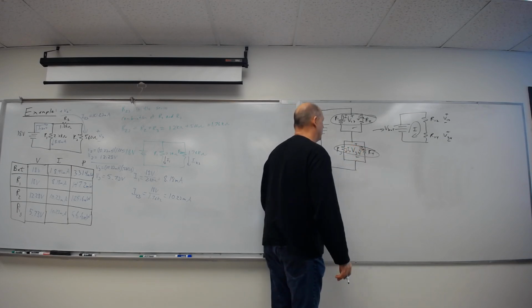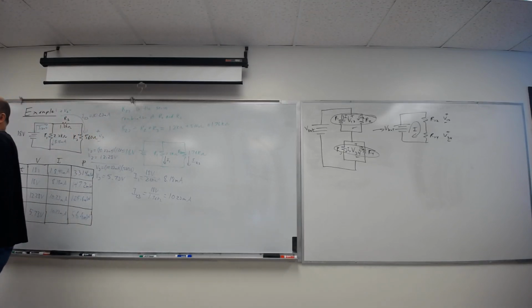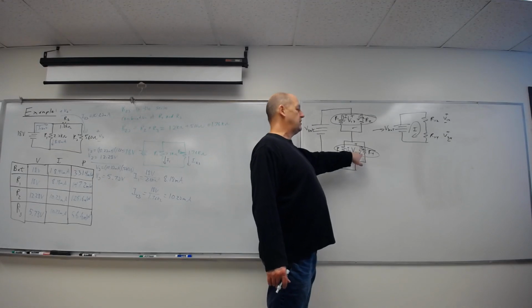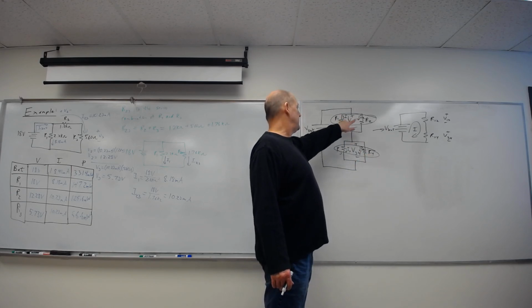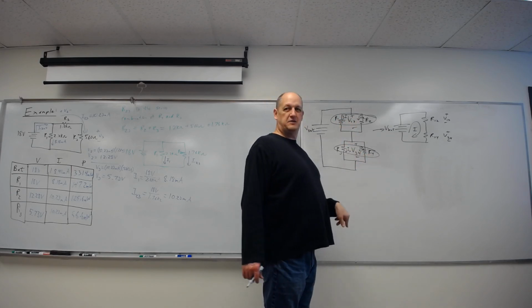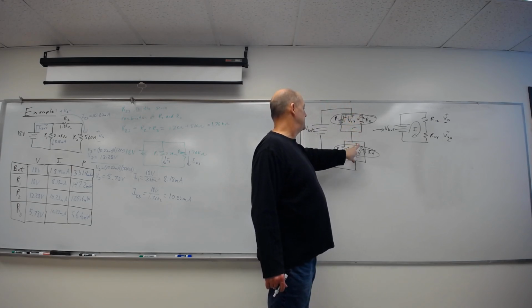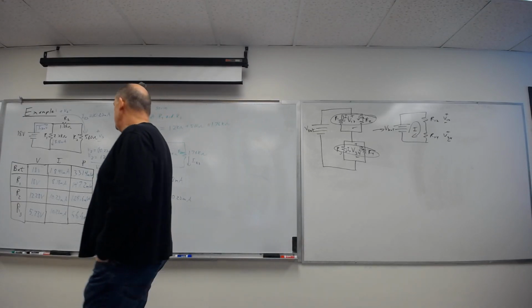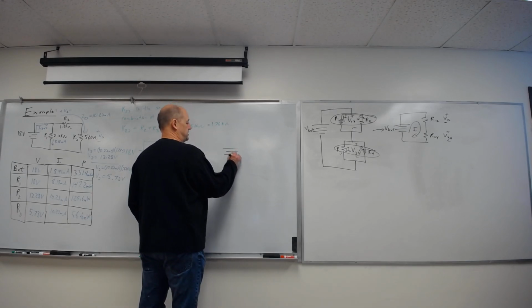So read that one close, because you're going to have 4 different currents you're going to end up with. Actually 5 if you count the battery. So think about this. These two currents, I1 plus I2, have to equal I3 plus I4. Neither of these will be equal to either of these, but when you have a current that flows out of the battery, splits, goes through these, comes back together, splits, comes back together. You have some other problems in the homework that look like this. These are just to make sure you can handle them.